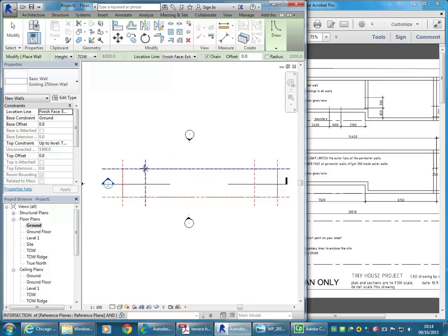So I'll just go ahead and do this, and then I'll give some time to finish it off. So I'm going to start on the intersection at the top left corner where the building should be. With the wall, yeah, that's right, exactly, with line. Yep, that's right. And so there it's not the intersection on the corner of the property, but the intersection of that reference plane that you've put in, which is the corner of the building.